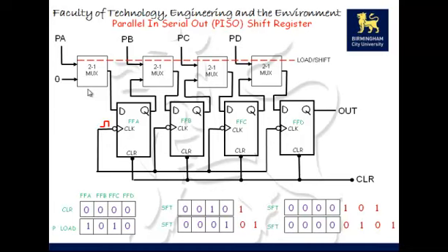Now, what's an application of this? An application of this is parallel to serial interfacing. This could be at the input of a microcontroller where you've got many peripherals connected to the input of it, but output of it is just one bit, which can go into a microcontroller. So it allows you to be very efficient in using the microcontroller pins. This is just one example.